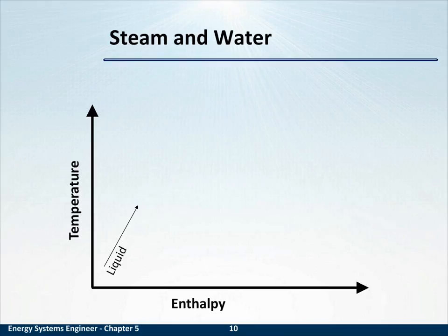This is the interesting graph that we referred to earlier when I said the difference between saturated steam and superheated steam. I mentioned that with sensible heat and latent heat, we'd see a graph later that gave you a visual to those definitions. Let's say, for example, you have a liquid, and as you heat that liquid, the temperature goes up. At some point, it begins to boil, and the temperature stops going up. Boiling water is 100 degrees C, 212 Fahrenheit. It doesn't get hotter. The energy of the system increases, but the temperature does not go up. At some point, you now have only vapor. You have heated it to the point where all the energy in the heating has converted all the water or liquid into vapor.